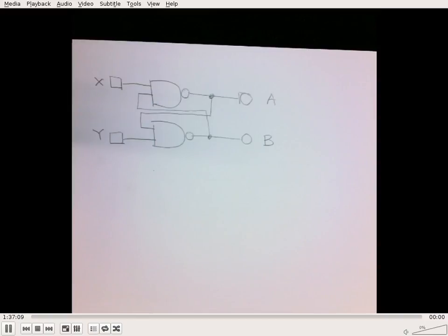Okay? All right. Now, because this is a NAND gate, it is essentially still having an AND gate inside it. It's just negating the output, which basically means if any input of any gate is a 0, the output is going to be a 1. Because it is inherently a negated AND, and with any type of AND, if at least one input is a 0, the output is going to be a 0. But in this case, because it is negated, an output of 0 of an AND gate becomes an output of 1.